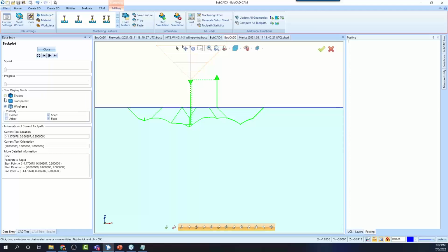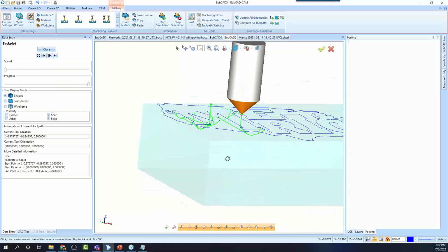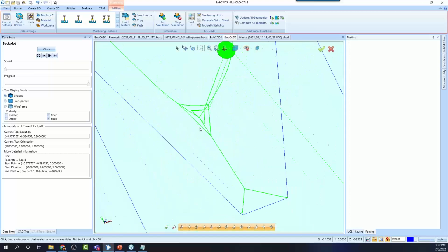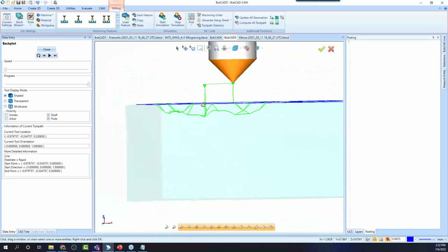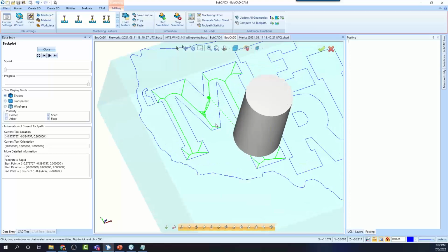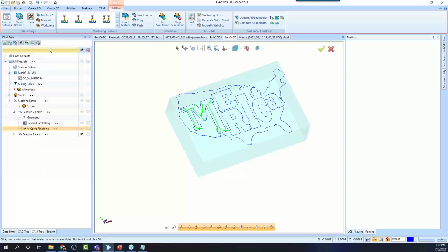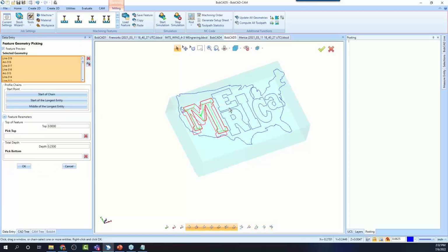Essentially, what's happening here is we're using this V cutter, and it's calculating the center. The width of the geometry you select determines the depth. So essentially it's going to come up in these corners and do a cleanup. You can see the bottom of it. We weren't quite at the total bottom, but it does a little cleanup move there. Again, you can use this for lettering. It's actually pretty easy to use, and it does create a good result.